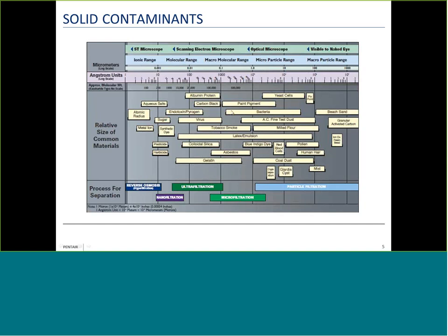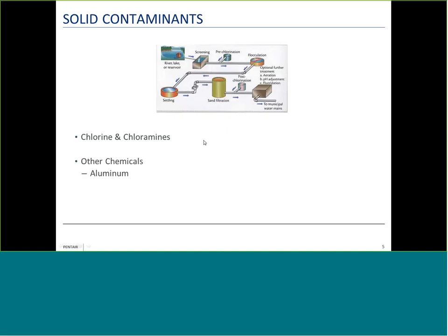But it will also help cause material to stick to the surface of your filtration equipment, and that aluminum doesn't stop working when it's in solution just because it's trapped on a filter. It's going to pick up particulates on the way, causing a fine filter to become even finer over time, leading to short filter life. Then there's pH adjustment, which can impact filtration when it's done to a high enough level.